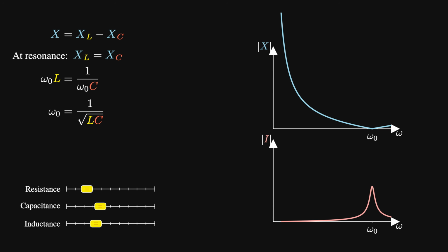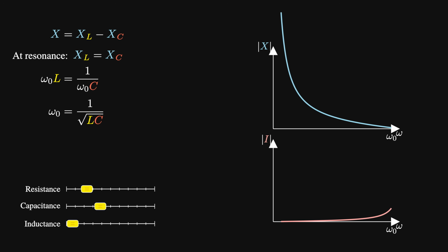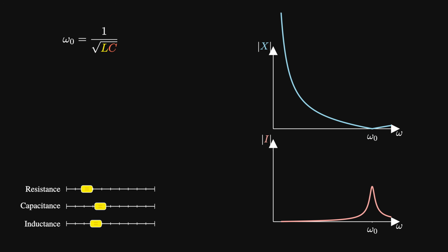But you may see that the curve changes a little differently when we vary the inductance compared to the capacitance. Inductance also widens our resonance peak. Now, as we said earlier, the RLC circuit does not necessarily cut out all the other frequencies beside the resonant frequency. If the peak is wide compared to its height, it doesn't really matter what the resonant frequency is, because we can't even distinguish it from the other frequencies. We can see this here as we vary the resistance. So the width of the peak matters too.